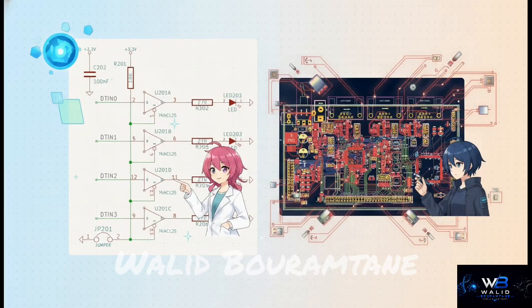Think about the fundamental difference between a symbolic blueprint and a complex physical layout. In the KiCad workflow, you always draw the schematic first. You're using basic shapes, right? Zigzags for resistors, maybe triangles for op-amps. This just shows exactly which components you're using and how they connect. But then, we have to move to the physical realization of that schematic.